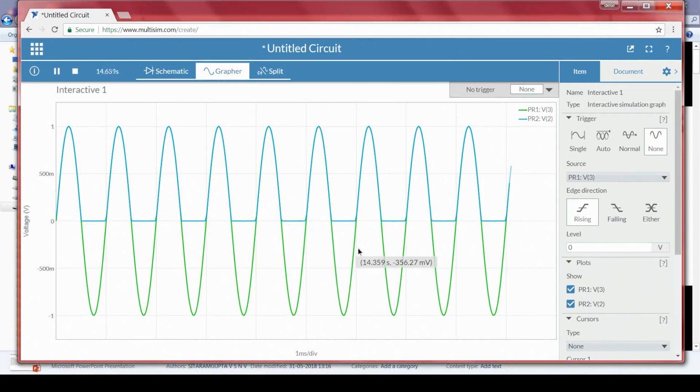So, even if you consider the ECG signal in the same way, only the positive portion of the ECG signal will be allowed and the negative portion of the ECG signal will be removed. So now it is easy to understand the positive peak from the signal, and we can set a threshold.